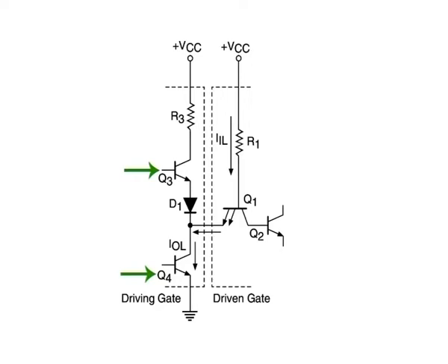When either of the two inputs or both inputs are in the logic low state, the base-emitter region of Q1 conducts current, driving Q2 to cut off in the process. When Q2 is in the cutoff state, Q3 is driven to conduction and Q4 to cut off. This produces a logic high output with VOH minimum equal to 2.4 volt, guaranteed for minimum supply voltage VCC and a source current of 400 microampere.